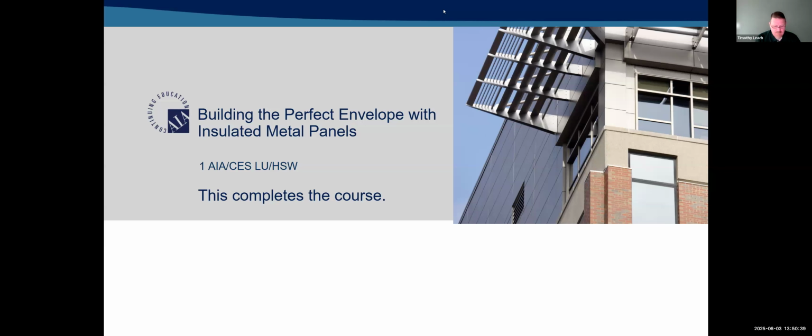If you have dead airspace, like if you have insulation where it can hold that moisture and accumulate that moisture, then I'd be more concerned with that than I would just an airspace with gypsum on the inside and the insulated panel on the outside. You should have very little concern of moisture buildup in that situation because the insulated panel is providing a nice, if the inside is warm, the insulated panel's inside face will be warm.